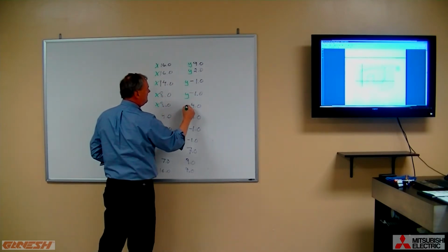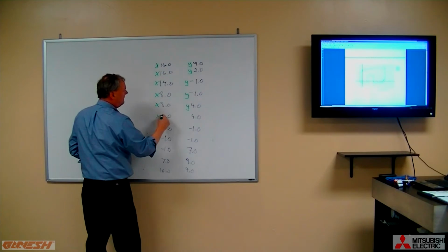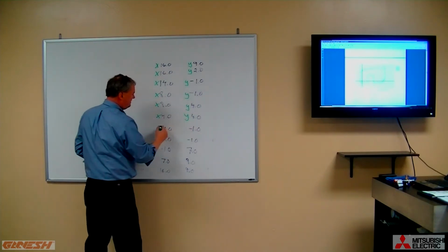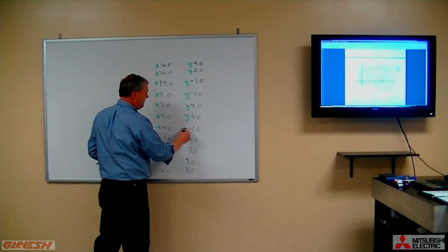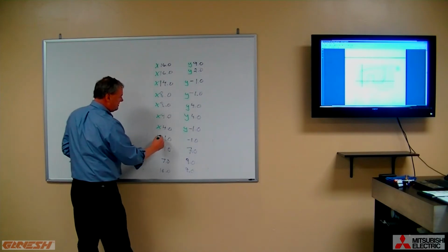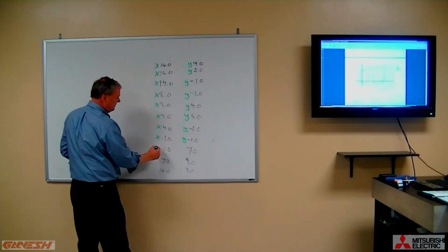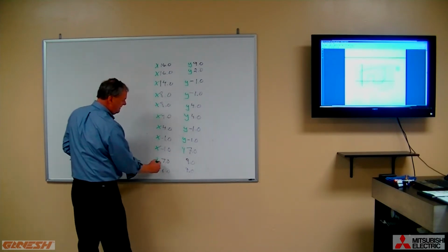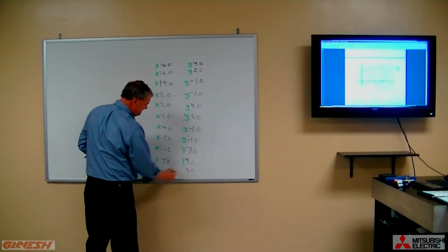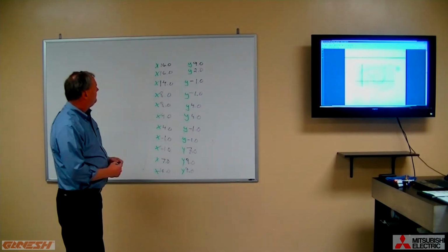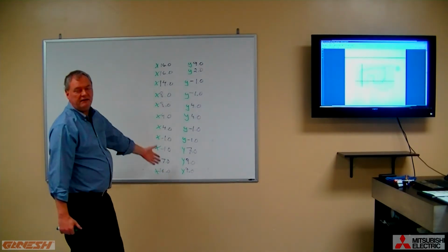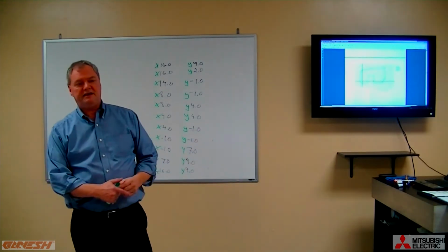Well, there's many things missing still, but the point being that to make this a valid NC program simply requires an axis address if you want the axis to move, and then a value that you want it to move to. So we now have a valid NC program. It's just that simple.